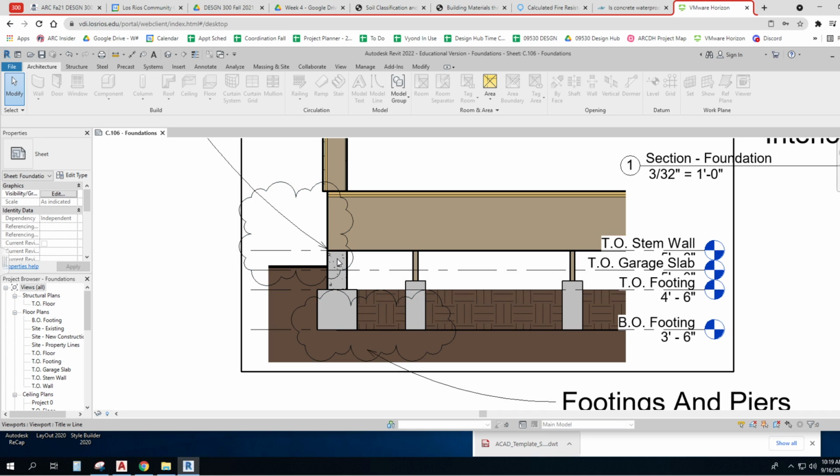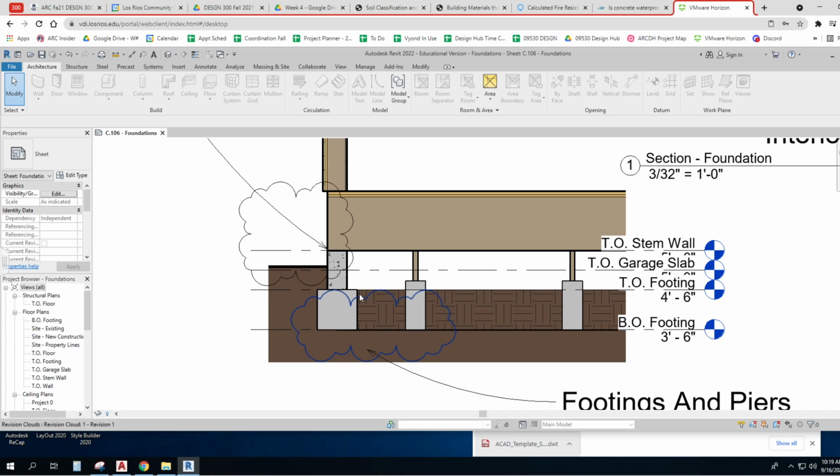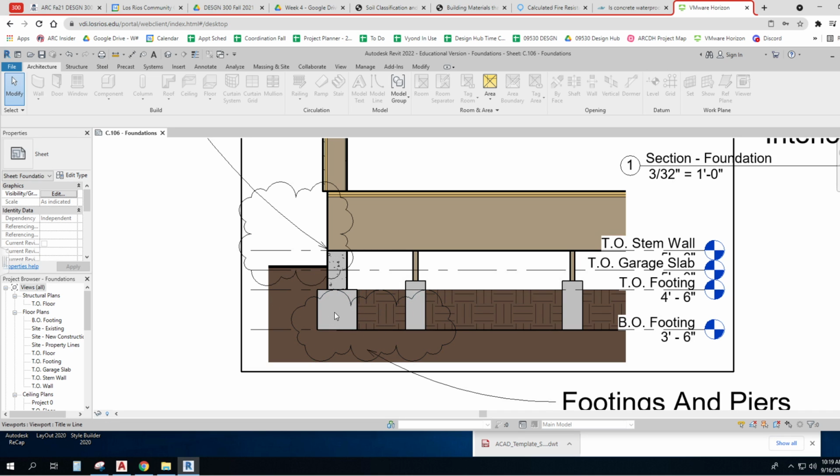And you can imagine it's just to save money and save materials. There's no need for all of this strength all the way around. It's just too much. 12 inches wide, thousands of pounds per square inch that you could hold when I need 15 or 20. So they take the stem wall, and the stem wall thickness is set by what you're going to sit on it. What size wall are you likely to put on it? How big of an area does the joist need to sit on to take the load?